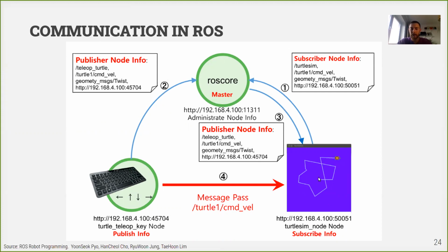And you remember this example we launched last time. There was turtlesim node. There was teleoperation key node, which allowed us to control the turtle with a keyboard. And that is how this system worked, actually. In the first place, when we launch our simulation, it tells ROS core, the ROS master, which is some kind of DNS server, you remember, that there is a node called turtlesim.